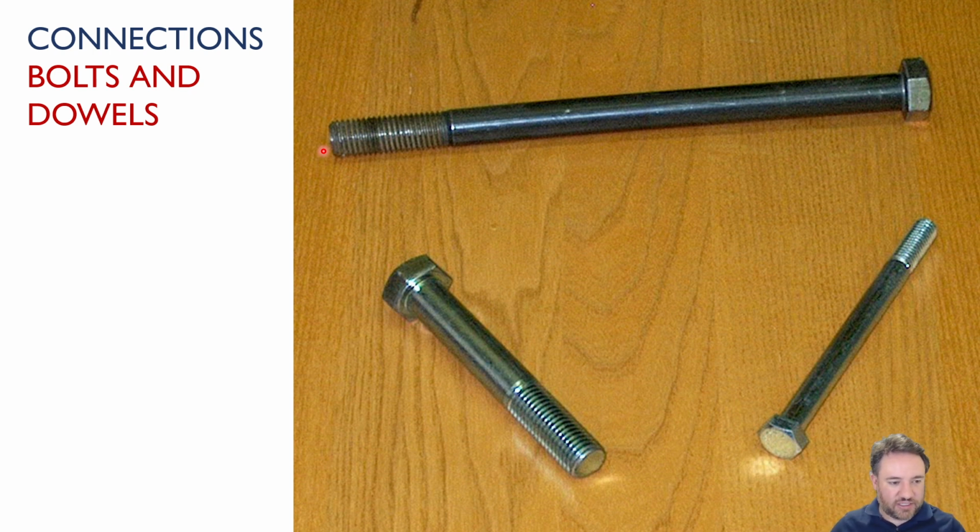In terms of ductility, bolts can provide some ductility, but it really depends on the size of the bolt. When we talk about bolt design, we're going to talk about all the different ways that bolted timber connections can fail. A ductile way is one of them, and that is a desirable failure mechanism, basically where the bolt bends inelastically, bends permanently, and that dissipates some energy.